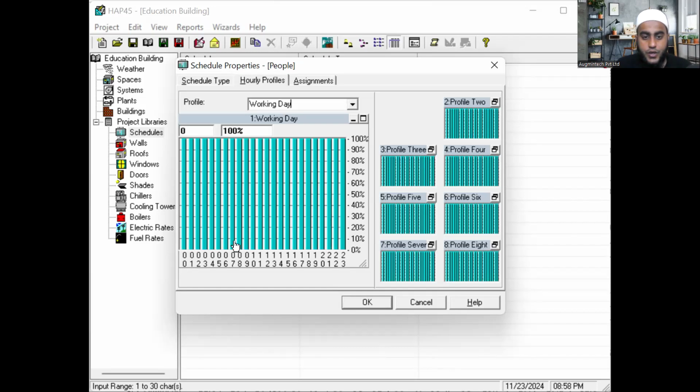Tell me please. So suppose your working day, for a school building, starts from 8 a.m. morning up to 4 p.m. Before that, up to 7 a.m., we do not have any people inside the school building before 8 a.m. So just select this profile manually, or otherwise write down from zero to 07, and automatically the profile is selected.